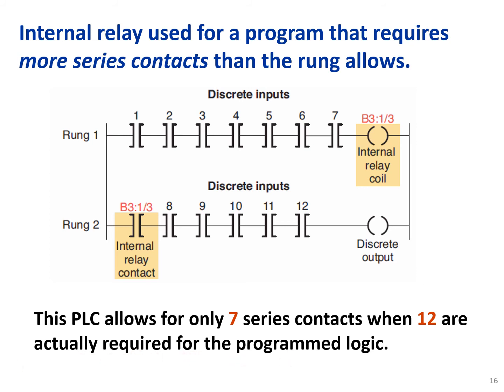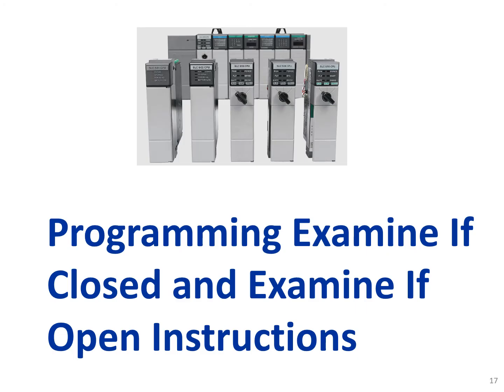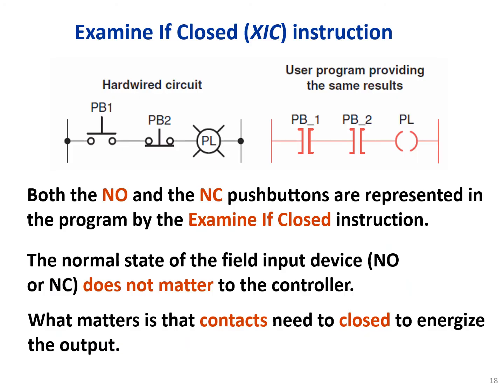Programming examine if closed and examine if open instructions. Examine if closed, or XIC instruction. Both the normally open and the normally closed push buttons are represented in the program by the examine if closed instruction.